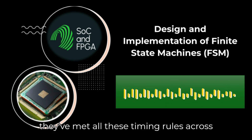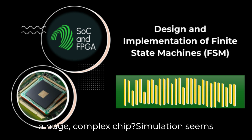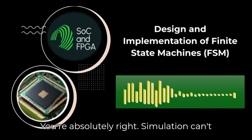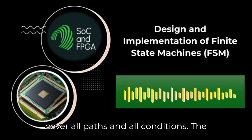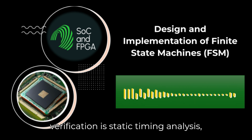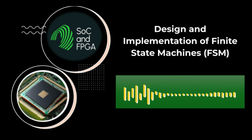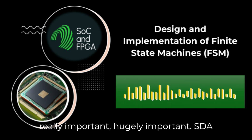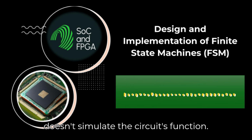So how do they know if they've met all these timing rules across a huge, complex chip? Simulation seems impossible for checking everything. You're absolutely right. Simulation can't cover all paths and all conditions. The absolute cornerstone of modern timing verification is static timing analysis, or STA. STA again, so this is really important. Hugely important. STA doesn't simulate the circuit's function.